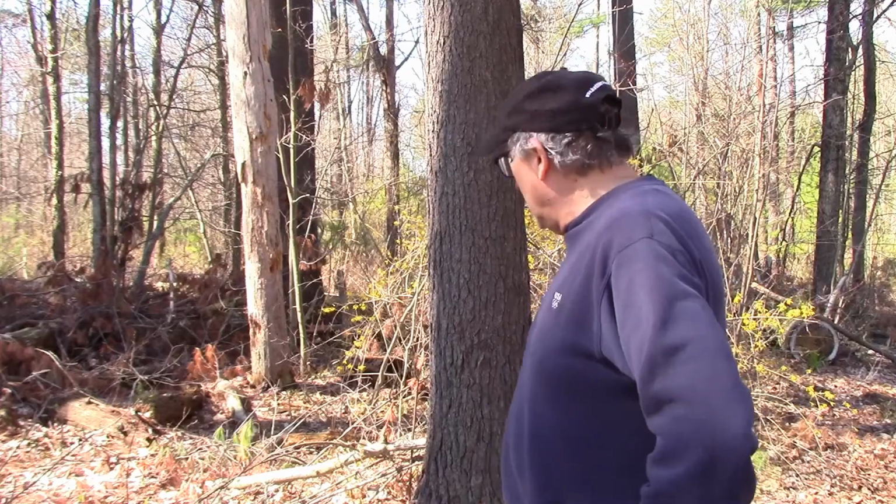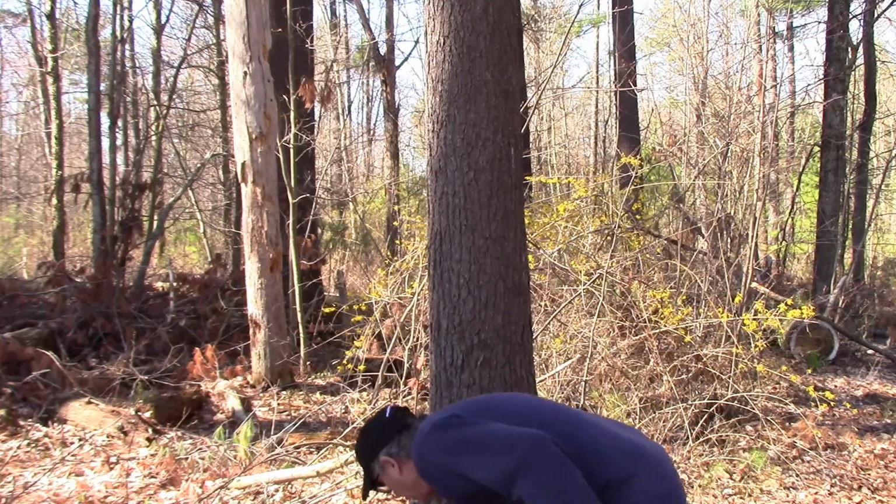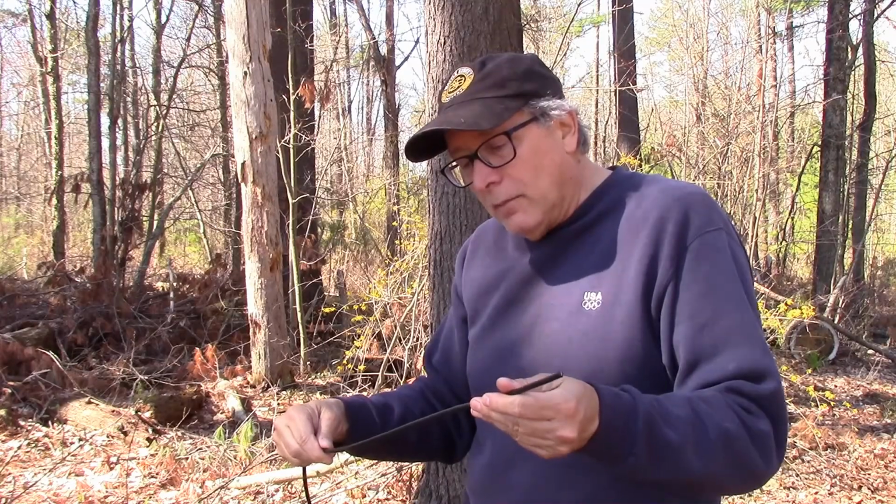I wanted to show you guys a simple antenna project. This is an 80-meter ground plane antenna, full size. Basically, these are all 65-foot pieces of number 12 copper wire. And it's going to be elevated radials. And for coax, I've buried some LMR 240 coax. And this is the DB style, the direct burial style, so it's just buried across the yard. This stuff may look small, but believe me, it can handle some serious power. And it's a fairly low loss cable.